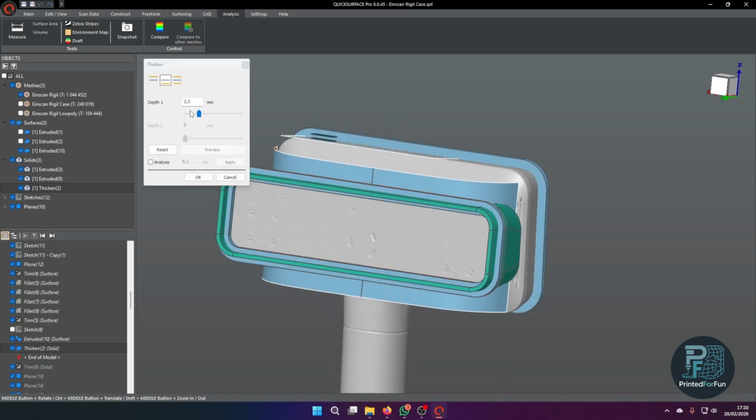So this is my goal for protective cases: 2.5 millimeters of TPU with 2 walls and a low infill is a bit cushiony, but also quite sturdy and protective. And you could even go thicker, but then you create the problem of the scanner not fitting in the case anymore. So I didn't want this.